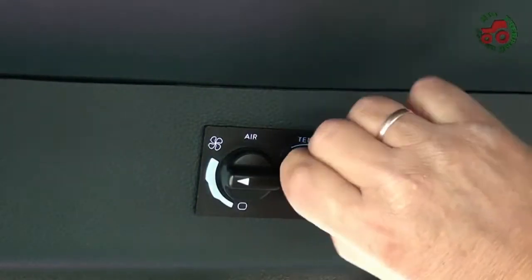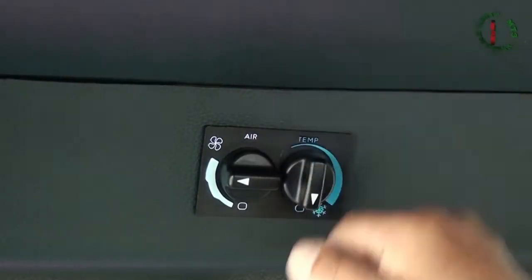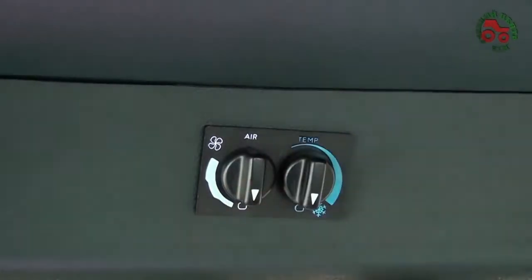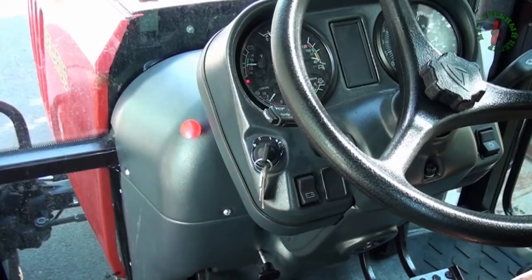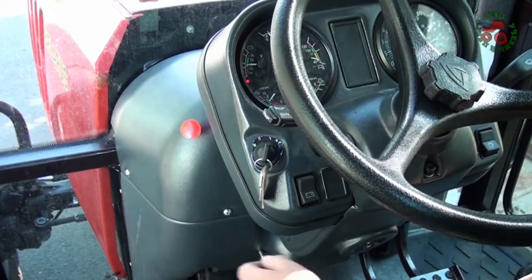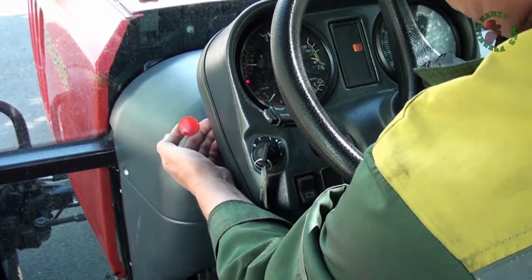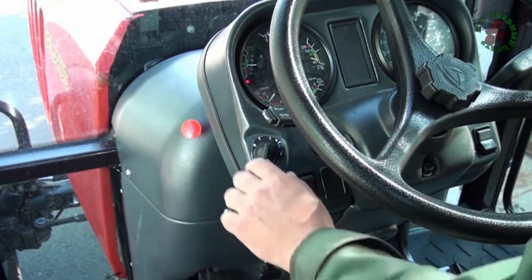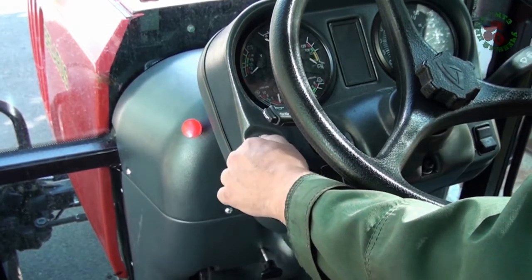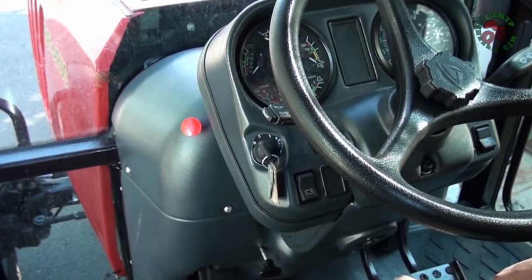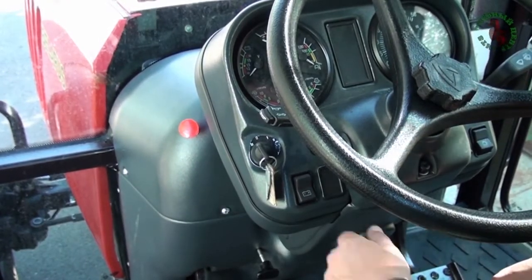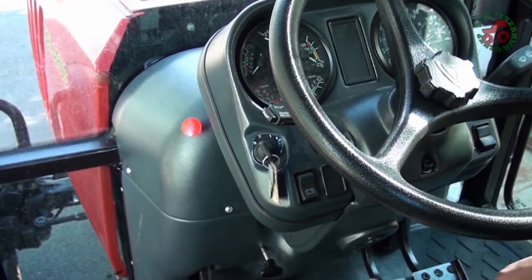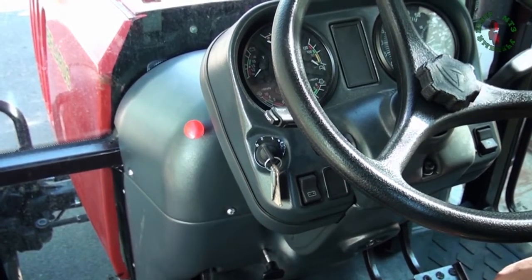Turn the conditioner or heater off. Pull the engine stop handle, if installed. Turn the key of the starter and instrument switch from position 1 into position O. Deactivate the accumulator battery when the engine is stopped for a long time.